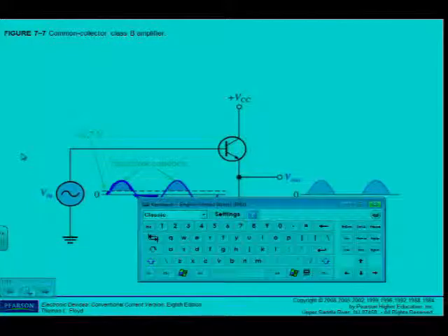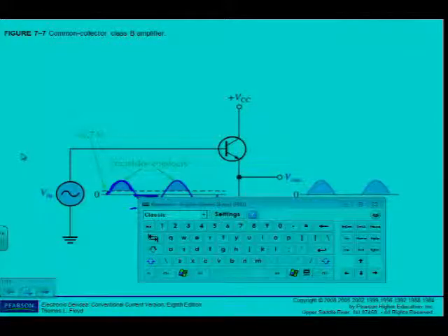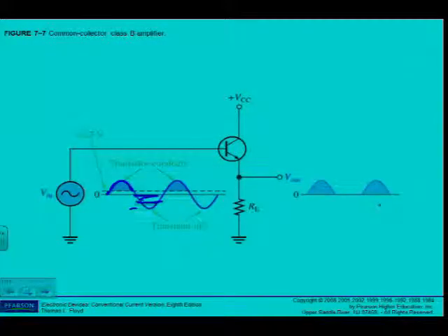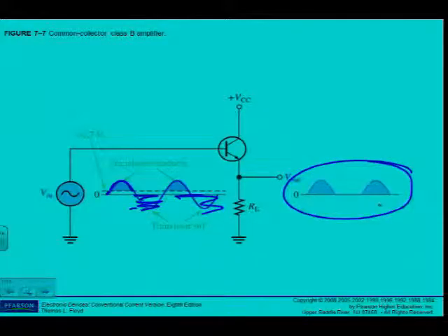So all these go away, are not amplified. So you can see what the output signal looks like. Alright, so you can see no biasing. When there's no biasing, so the Q point is at cutoff, then it's a class B amplifier. You have to be able to draw this and the input and output waveforms with a simple explanation.